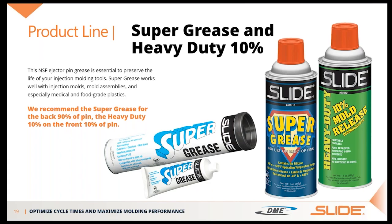So what was happening was it would wear out, kind of dissipate. The heat would make it start breaking down, and then they would spray WD-40 in there to keep going through the shift. Well, then you've got double trouble, because you've got a solvent going in and attacking what was already an inferior grease. So in this case, this customer just switched to the super grease, period. They use super grease on the whole ejector pin, and it solved the problem. We see that type of thing every day. It's just a great product. You just need to try it out.